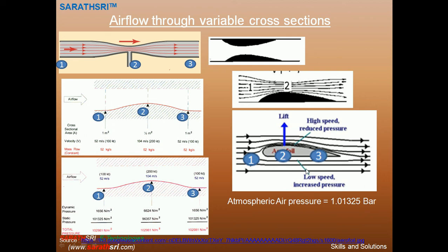Here the pressure is about normal, or higher than at this place, so there is a possibility of a force being generated in this direction. As pressure always points towards the surface, but here the pressure is low, it is away from the surface, so it lifts the surface in this direction. This is nothing but producing the lift.